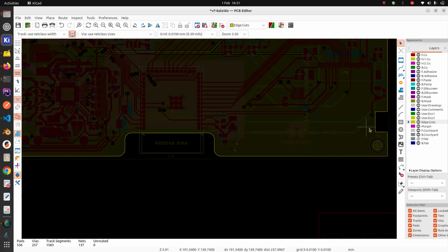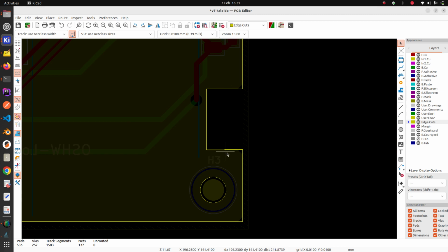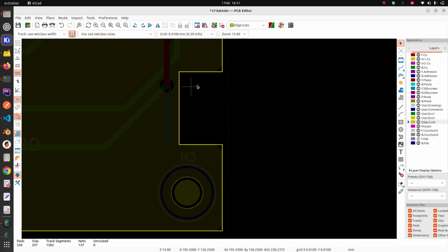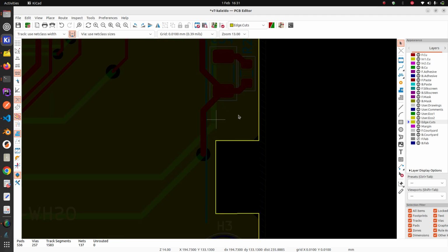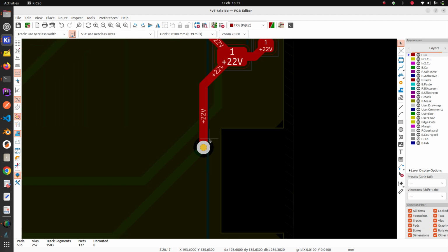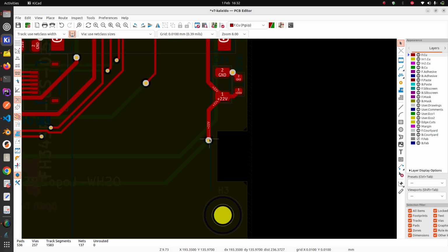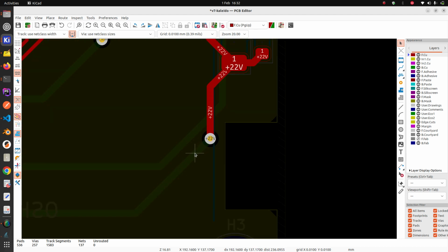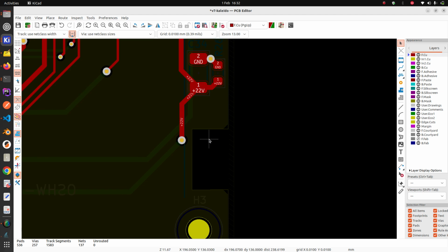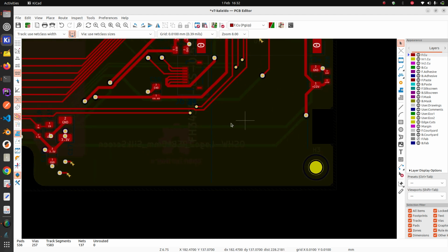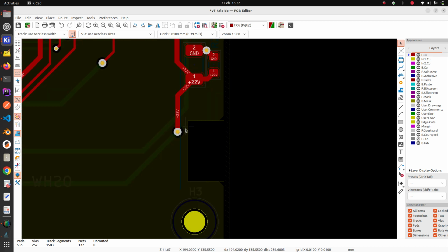And take care, for example, when you make cuts in the PCB, because you might get too close to the traces themselves. This is actually not perfect. I won't do it now, but this should be a bit away from this cut, because if for some reason the FPC cable that's going to be connected like this doesn't reach the end, and you have to remove a piece of material, then you're going to cut the trace.